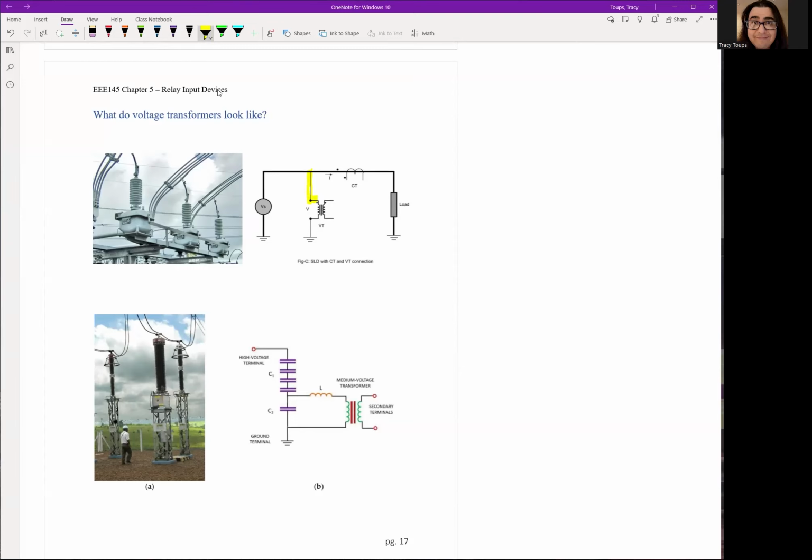So you tie it to the main line, but then it just draws out. So in this example, you have the main conductor, which is the bundles up here. We're going to have a small little wire coming out. This is your wire to your VT. It's going to go through this little coil, this insulator right here. So this is what the wire hanging off the main bus looks like.